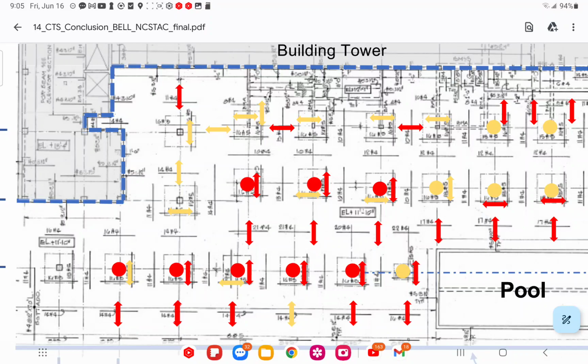I've got two ways to get there. One, the rebar, these number 4s, comes across and goes to the joint. There's some overlap from this joint just to there, a little small piece, and it's able to act in cantilever and stay up there. Don't like that one. That one's just stupid. Doesn't work.